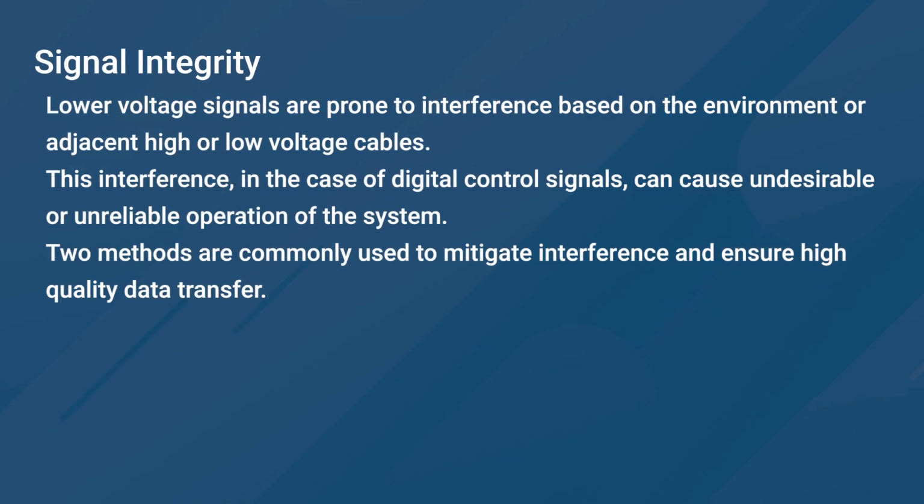Preserving the integrity of either analog or digital low voltage signals is critical, since we want to maintain reliable and replicable control of our lighting devices. Since the environment that the cable is installed in may have sources of electrical noise, either electrical or magnetic, in close proximity to the cable itself, we have to take steps to prevent this noise from affecting our control signal.